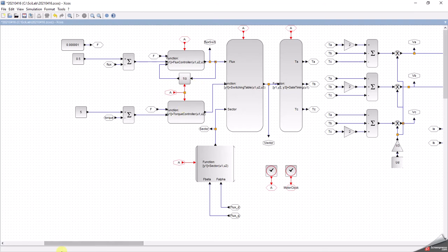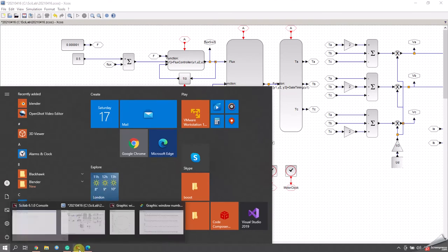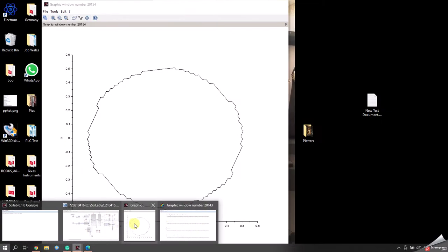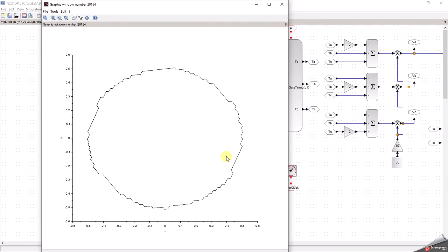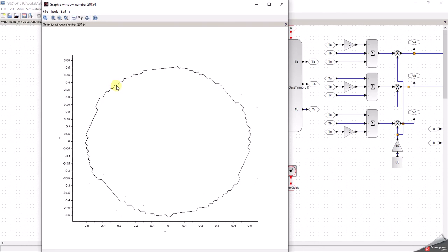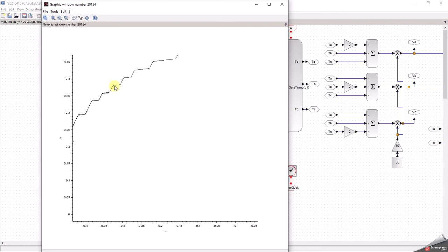So like I said, that's telling me that this thing is doing what it should be doing, switching things on and off, on and off. So this is the bang bang controller, something being switched on in that direction, then switched off, and then switched on in that direction, and going around in a circle. So there's an imaginary circle over here, and there's a dead band in between these two. From there to there is your dead band.